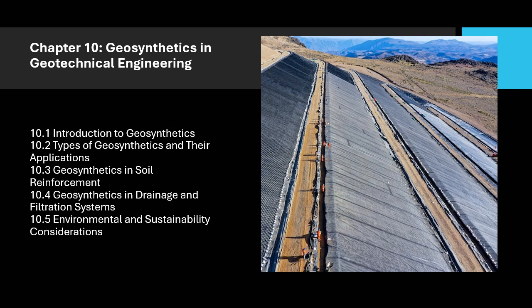Geocells. Description. Geocells are three-dimensional, honeycomb-like structures made from high-strength polymer materials. They provide lateral confinement to the soil, which improves its strength and load-bearing capacity.